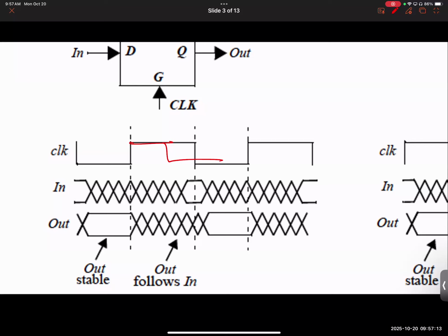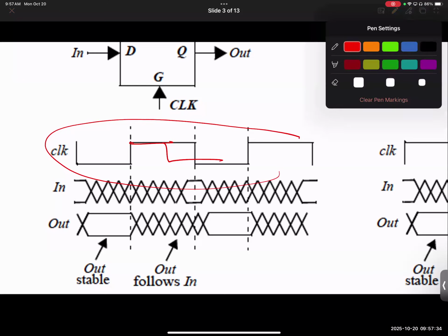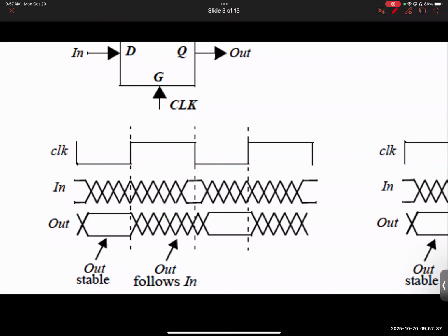Similarly, in a circuit, in a huge chip, when different components are all in different location, how can you synchronize their work? You can use a signal like this, clock signal. Please pay attention because I was anyways going to cover it. It's not just for the question, okay? So it should also interest everybody. Notice, you can make your circuit respond only when your clock is activated. And you control when your clock is activated, right? So you can control its time period, it can control its duty cycle.